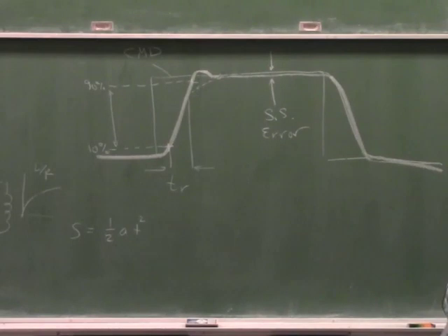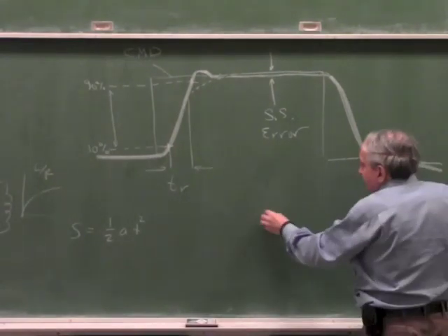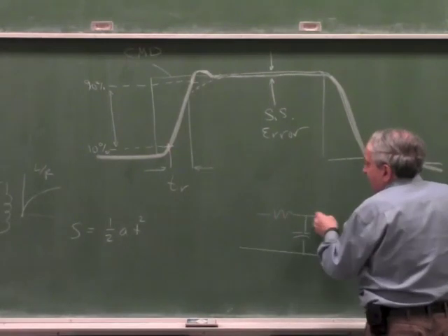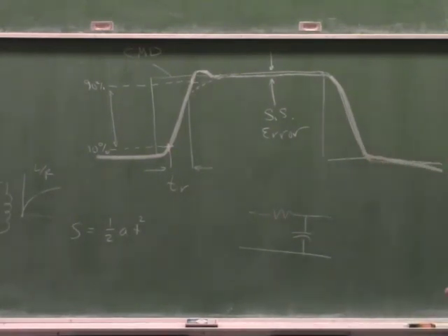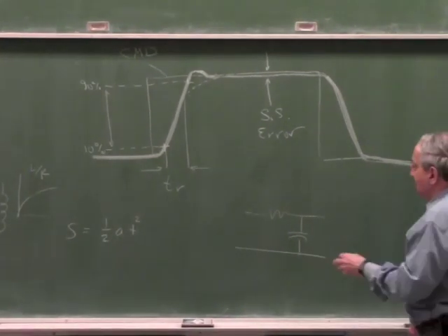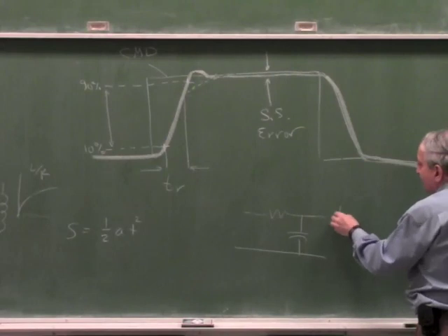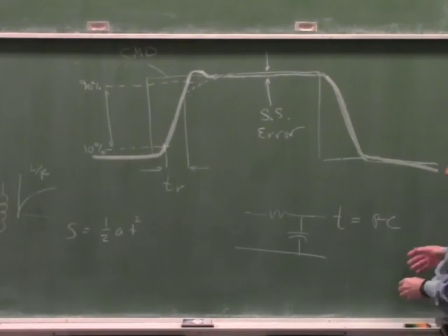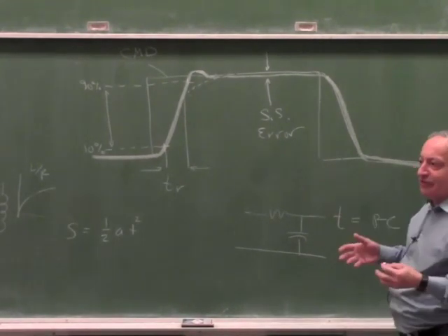Now, one big area of confusion is when people do calculations. Let's say you have a simple first order system which behaves like an RC, a single pole system. So when people do some calculations, they say, just a second, we learned at school that the time constant of this equals RC. And then if they draw it and they compare it to the rise time, they get a different value.